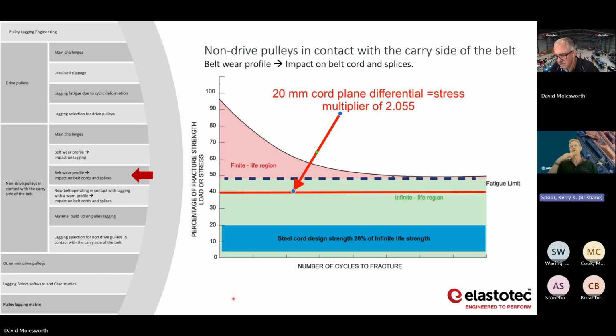And that belt is right there on safety factor. So all of these things that you're indicating with the pulley wear may start to play in differential tension profile around the drive pulley if a belt is right on, or perhaps I say a bit under, the safety factor.